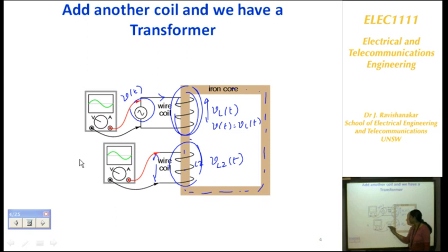This voltage will appear across this coil, and when you use an oscilloscope to measure this voltage, the oscilloscope will give some reading here. This voltage will also be an AC voltage, and since the current is at one particular frequency, the flux is also at the same frequency, and hence this voltage will also be at the same frequency. So this is what is called the transformer action. In the transformer, by the process of induction, the voltage is induced in the neighboring coil.